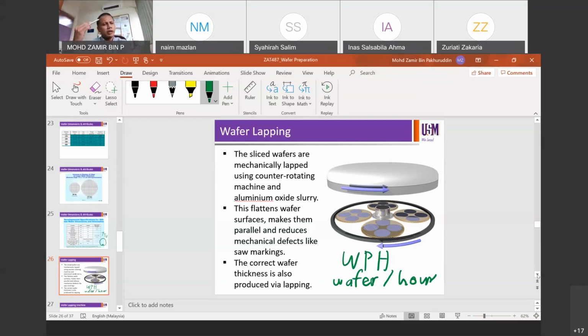Every machine in the wafer fab has its own WPH. If you have higher WPH, then you'll be able to produce more wafers in a week, in 2 weeks, in a month, in 1 quarter, in 6 months, in a year. If you work as a process engineer later on, or in fact an equipment engineer, this will be among the parameters that you work on, probably as one of your side projects. When I was in lithography last time, WPH was one of my main projects as well.